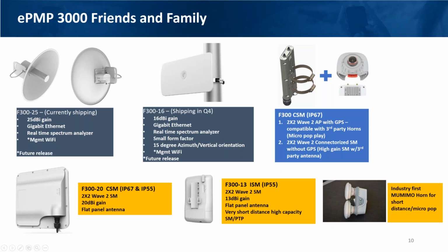The key message is this is not a long distance play. This is not going to give you a 5 kilometer range. It's an 11 dBi type product, 60 and 90 degree. But the vision we have is if you're in a dense, semi-rural, semi-urban place where you want to be below tree line or below public buildings, and you want to just light up a small 60-degree sector but still want to benefit from MU-MIMO, you pop one of these in.